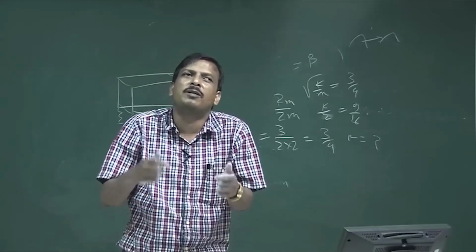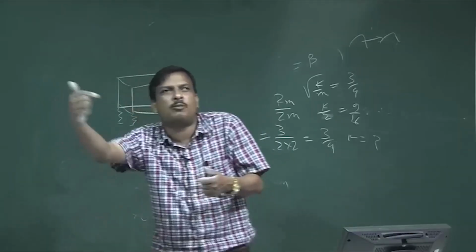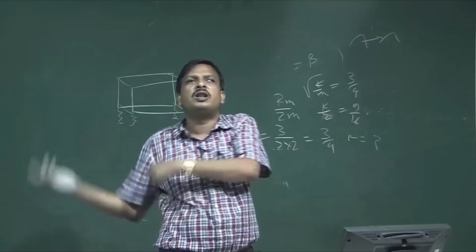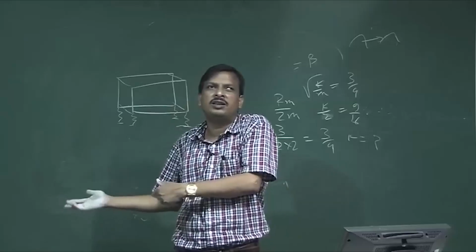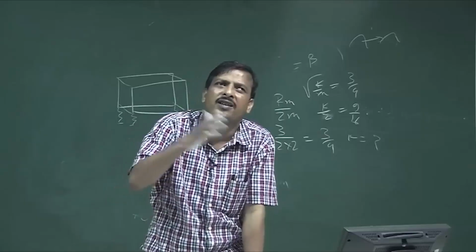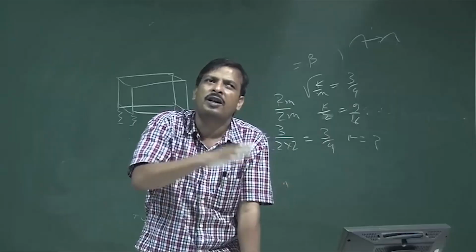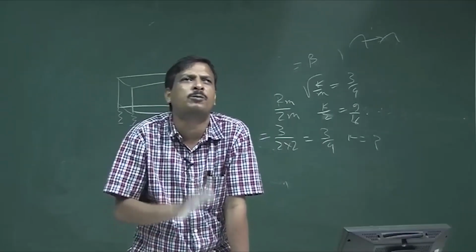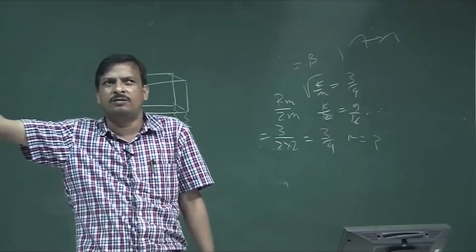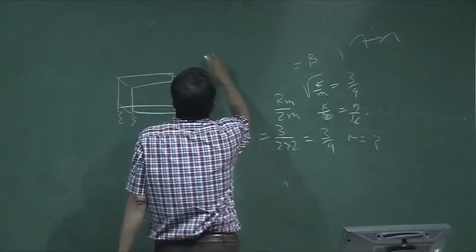That means, if I know the vibration frequency, or suppose that once the chiller plant is on, a force will be applied and I know that force frequency, if that frequency resonates with your system frequency, then what will happen? The chiller plant cannot be stable. So, I have to operate the chiller plant below the resonance frequency, or if I know the maximum applied force frequency, then I can make my resonance frequency well above that. Similarly, given a practical problem, suppose I want to design a loudspeaker.